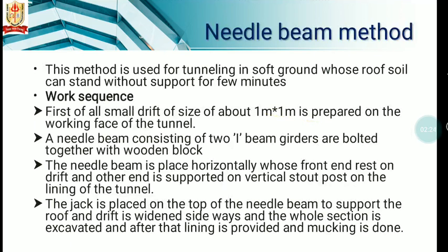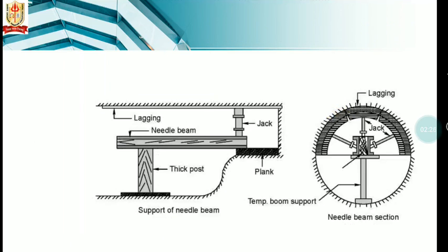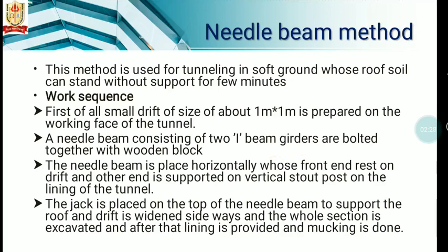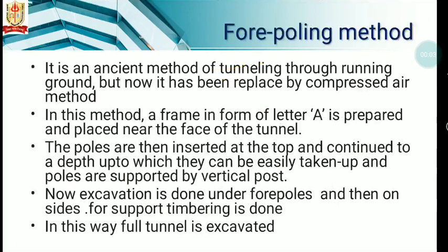Likewise, this is a jack. The jack is placed on the top of the needle beam to support the roof, and the drift is widened sideways and the whole section is excavated, and after that lining is provided and mucking is done.